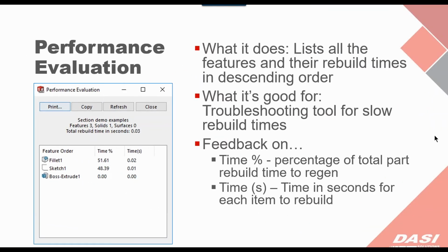Performance evaluation. So this is a cool one that's probably frequently underutilized, but it's extremely valuable. And what it does is it lists all the features and their rebuild times in descending order. The key thing to note is what it's good for is it's good for troubleshooting slow rebuild times. So great for parts or drawings if you've got long load times or if there's issues with certain areas of that file loading, it'll give you feedback on what is actually causing specifically that issue.